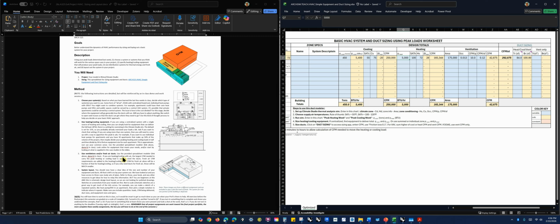So I'm not saying you can't have a centralized system, but you might want to do something more like the project that we did this week, the Candela Apartments, that has heat pumps and a centralized air column for individual ERVs in each apartment. You could do that. You could do even just single mini splits, really simple, with an ERV that's sitting on the exterior wall for each apartment. So you could really do it with probably no ducting or very little ducting. Or you could do some kind of combination.